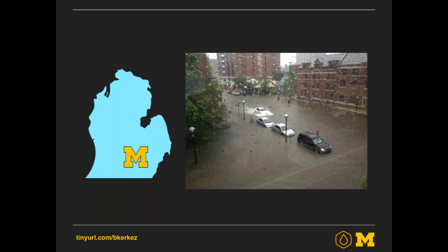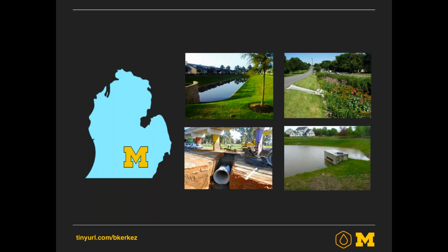And I really think there's a green infrastructure renaissance almost right now, this idea that a lot of these distributed stormwater management solutions are brought into place now where you do not have the ability to build massive infrastructure. So what you see are things that look aesthetically appealing, like ponds and green infrastructure and things that have been dispersed throughout, that the general public might not even know what they do, but they're there to buffer flows. Instead of having one large tunnel, you're basically deploying lots of little buckets throughout a watershed to capture this and to convey it.